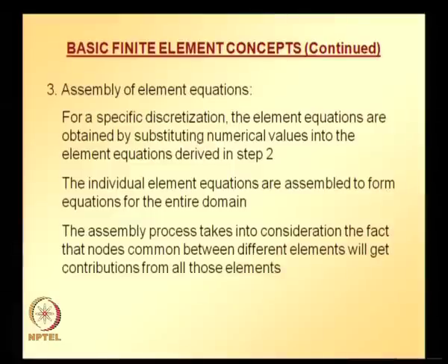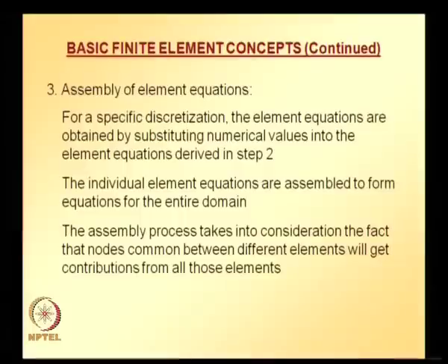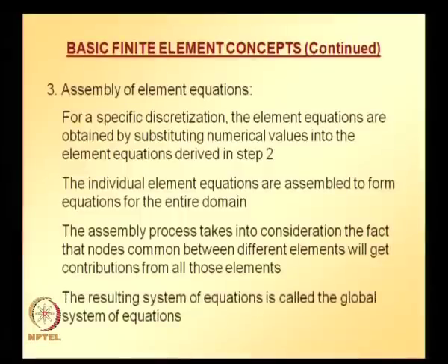Suppose a node is common to 3 elements, the contribution to that particular node in the global equation system comes from all the 3 elements. If a node is common to 2 elements, the contribution to that node comes from the 2 elements. The resulting system of equations is called the global system of equations.